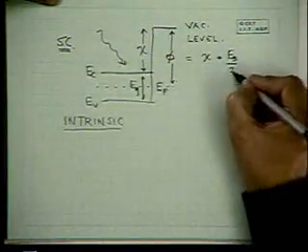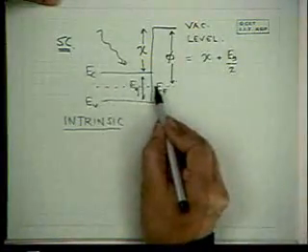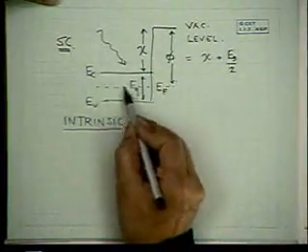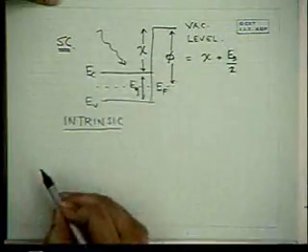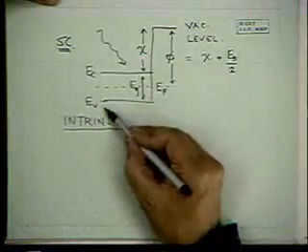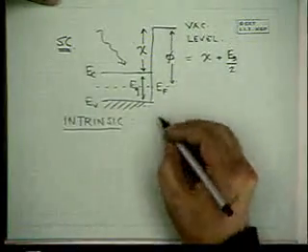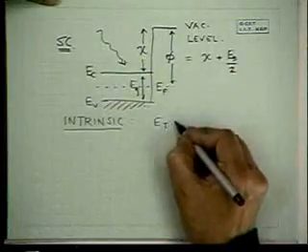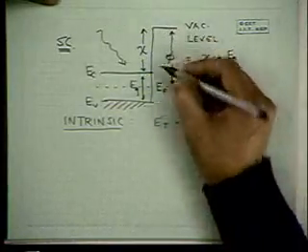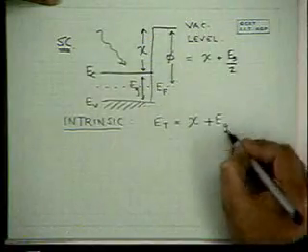Okay, but there are no electrons at this level, so photoemission cannot take place. There is no density of states. So the photoemission must take place from wherever there's a high density of electrons available, and that's the valence band. So the threshold energy in this case, Et, is chi plus Eg.